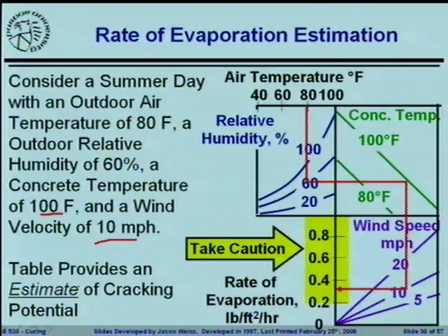All right, but the basic approximation that Menzel made was he said, bleed water on the surface of concrete is a lot like a lake. And what we're going to do is assume that if we can predict the evaporation rate off of the surface of a lake, we can get it off of the surface of concrete.